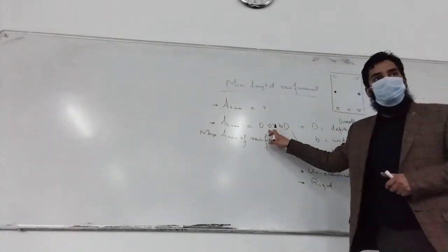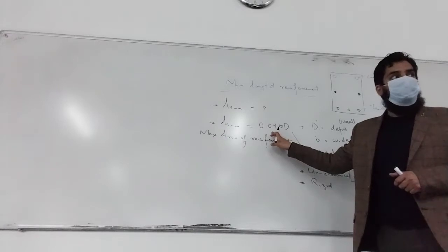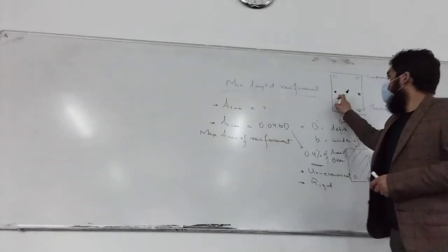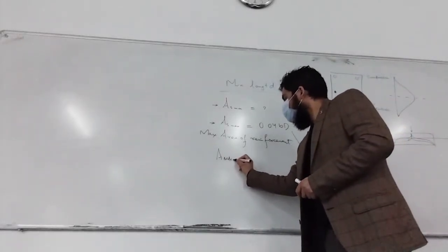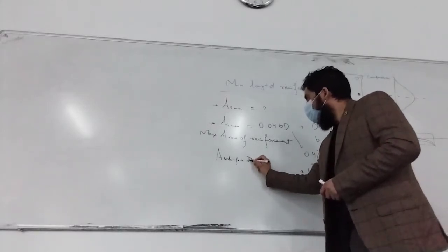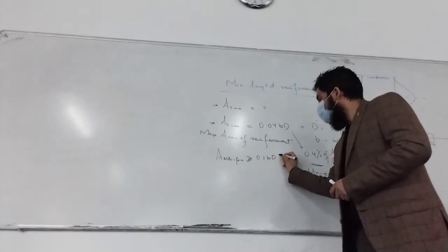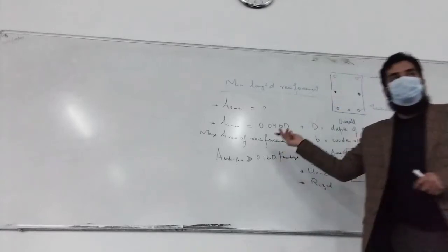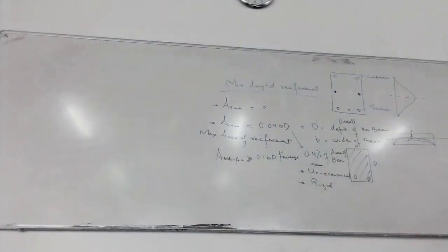This was 0.4%. You have tension reinforcement running as 0.4%. But the side face reinforcement which you provide has to be at least, or greater than, 0.1% of the web area. This is in percentage. This is the minimum. That was the maximum for the tension reinforcement.